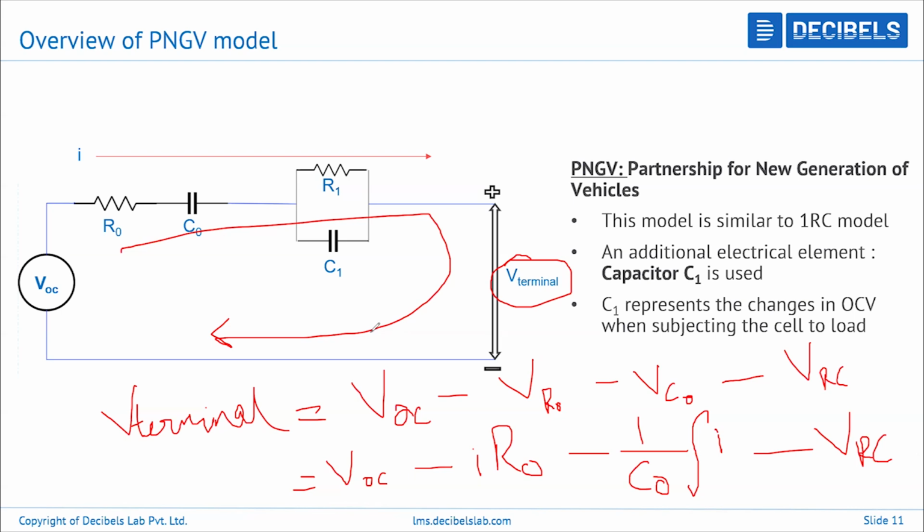So basically we know that the current across the branches R1 and C1, they change. So they become I2 and I1, right? Now utilizing I1 and I2, we can derive the total potential difference across this RC branch. Again, we know that the potential difference across R1 and across C1 is the same. Utilizing these two constraints, we can derive the total potential drop across the RC branch, right? So in short summary, the equation that we need is here.